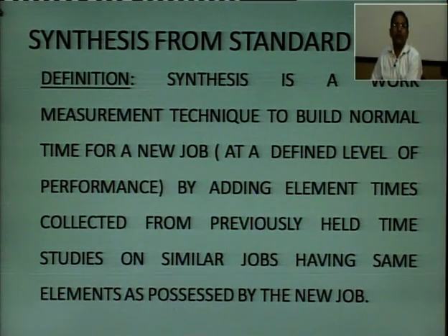Synthesis from standard data. Definition: synthesis is a work measurement technique to build normal time for a new job at a defined level of performance by adding element times collected from previously held time studies on similar jobs having the same elements as possessed by the new job.